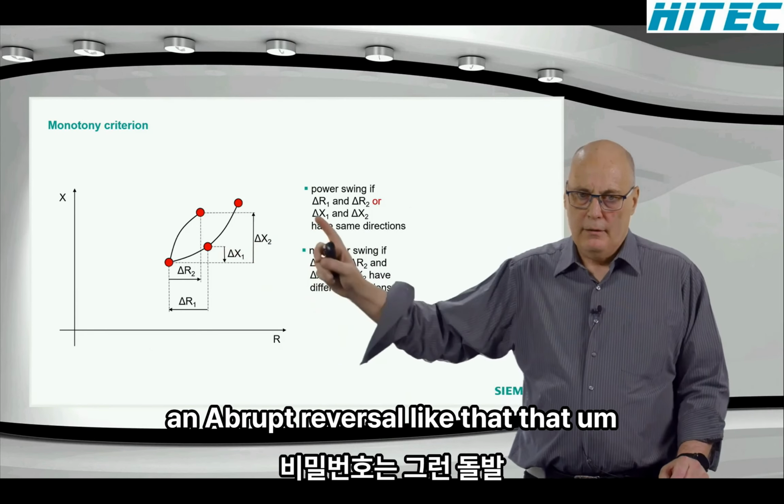But it doesn't matter. At the bottom, you can see the power swing blocking in the open pole is obviously reset, but in the 2 connected poles, B and C, the power swing blocking is active and prevents tripping during the 1 pole dead time. That's the fault inception. The power swing blocking resets. And that's the reclosure. And see, after the reclosure, the power swing continues and the power swing blocking becomes active again, and there's no tripping of the relay due to the power swing blocking.